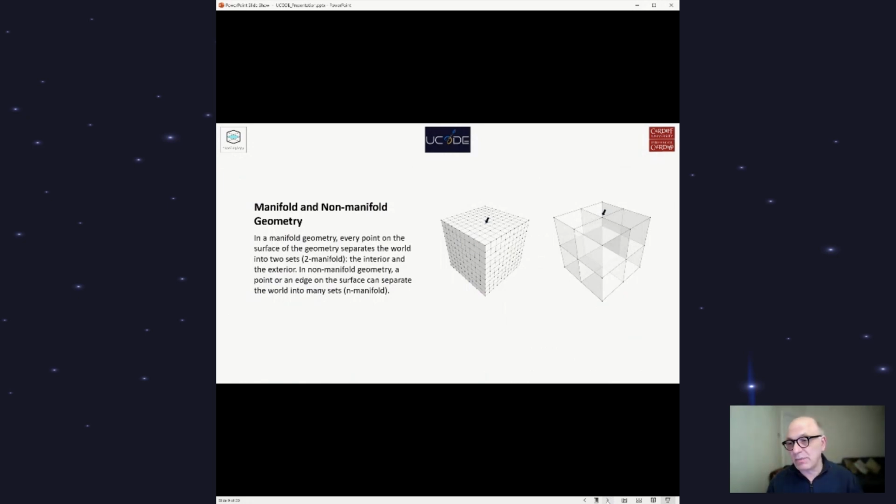This idea of non-manifold is very compatible with energy analysis, because all you need in these types of energy analysis is to actually look at how things are connected, or what surfaces separate spaces. And that becomes really important. So we wrote an interface from Topologic that talks to OpenStudio using the OpenStudio API that obviously runs EnergyPlus simulations, and we get the data back and we present it as color coding of the 3D model, all done automatically. And I will show you.